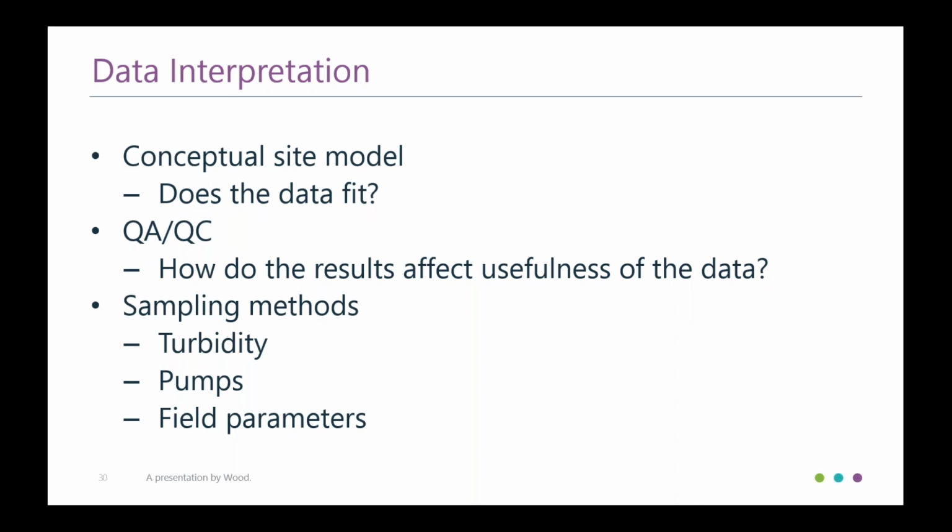And I have a great example of where they got all the way through remediation, set up a whole system, and the data didn't really fit what you should have thought was going on. And again, you have to take those QA/QC results every time you get a hit in one of your blank samples. You have to evaluate that against the sample results you've gotten on your well samples or your groundwater samples, and try to understand how that affects it.